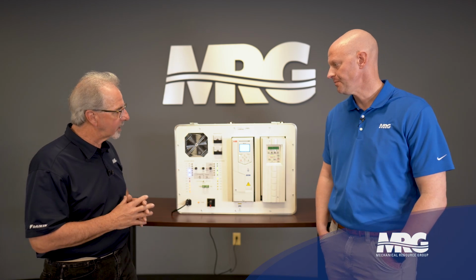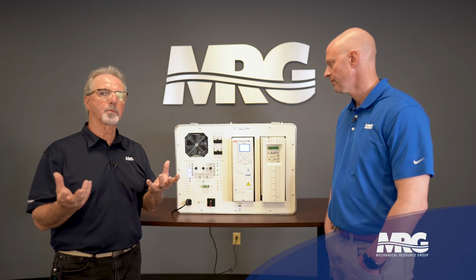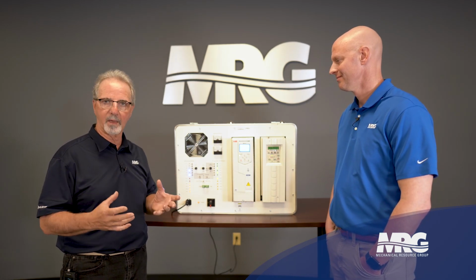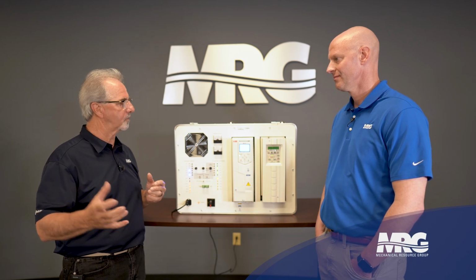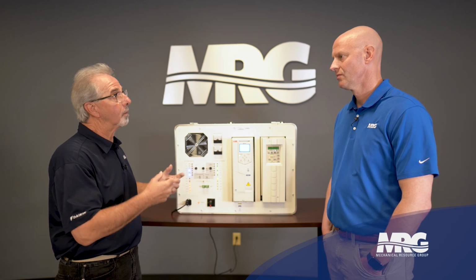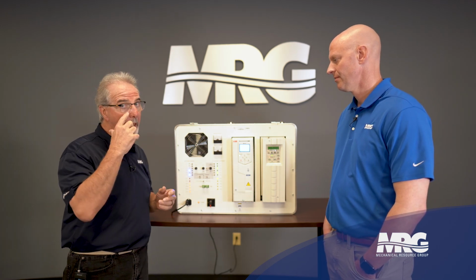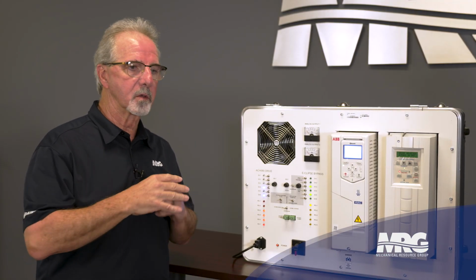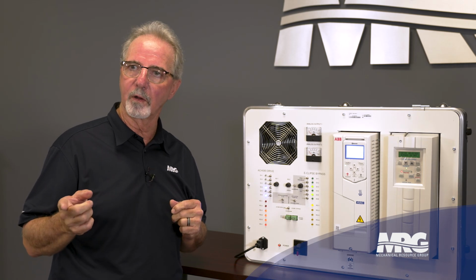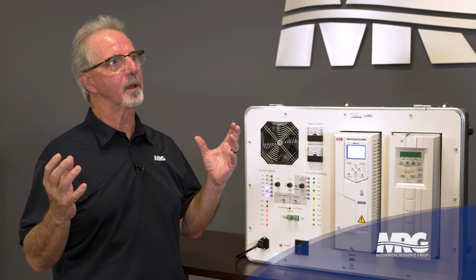Well, remember that the drive itself has to be considered a third-party device. I cannot control smoke dampers. I can't move any other mechanical device other than the exhaust fan or the pressurization fan. So I have this set up right now in what we call a PID loop. And when we get on the whiteboard in a second, John, I'll show you how that all interacts. Basically the building automation system is completely gone. These fans that are on stairwell pressurization and elevator pressurization only run when there's an event. They don't run any other time, okay?